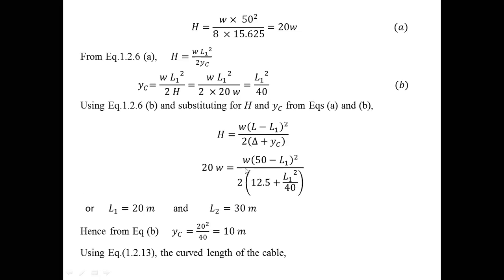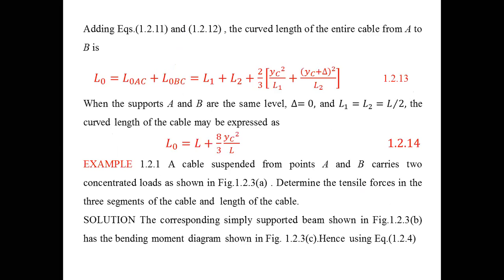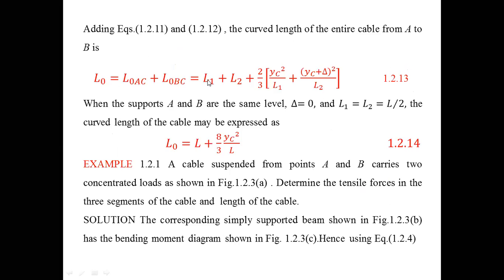Yes, sir. Now to calculate the length of the cable, already you know the L1 and L2 and YC. Then use the formula. What is the formula given? This one, formula 13. You know the L1, you know the L2, you know the YC, you know the delta. Then use this equation and find the total length of the cable.